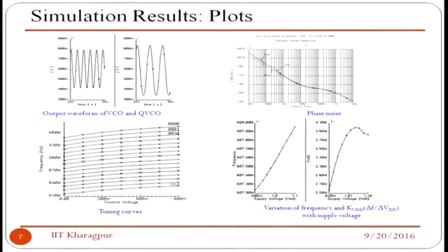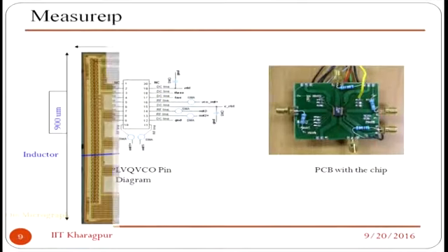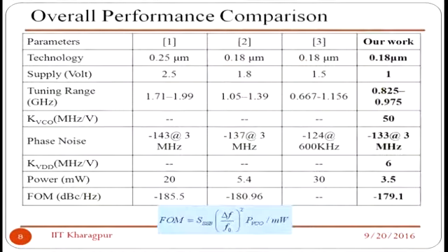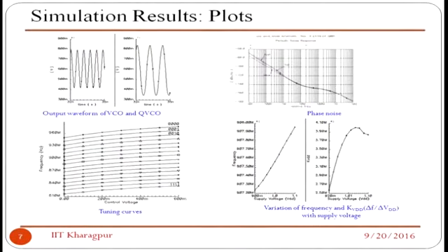And then you can look at the phase noise performance and the tunability. This is the most important curve which you have to understand carefully. So what is it that I want? This is the frequency tuning curve. This is the control voltage VC, and this is the frequency. So this is from 0, 0, 0, that is, all your capacitors are off, so all your capacitor banks are isolated. So your VCO is working with 1 by 2 pi root over L into C, where C is the varactor capacitance. So the capacitance is much less, and you will have the highest frequency.